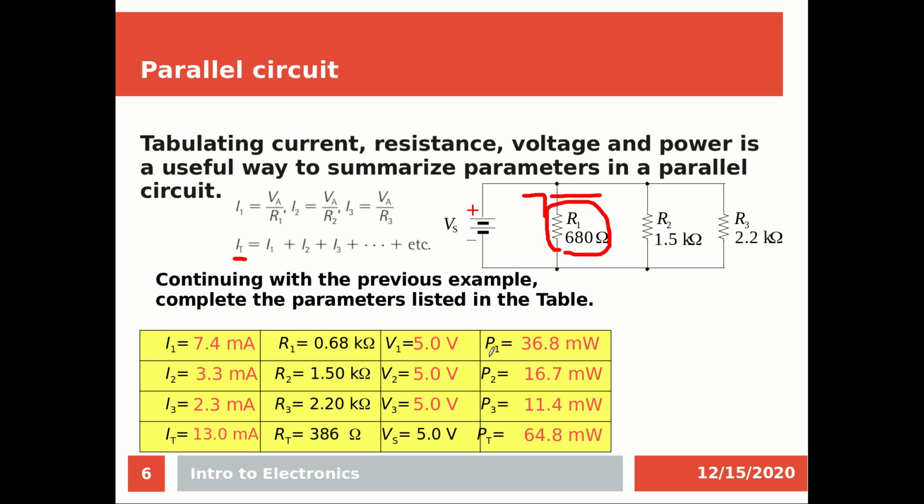Then you want to calculate the power. It is IV or VI. Then you have the VT and you have the IT. When you calculate it, you can calculate the total power, or you can calculate individually. You have the voltage, you have the current in each individual resistance, and you have the resistance, of course, so you can calculate the power in each resistance, then take the summation of all of them.